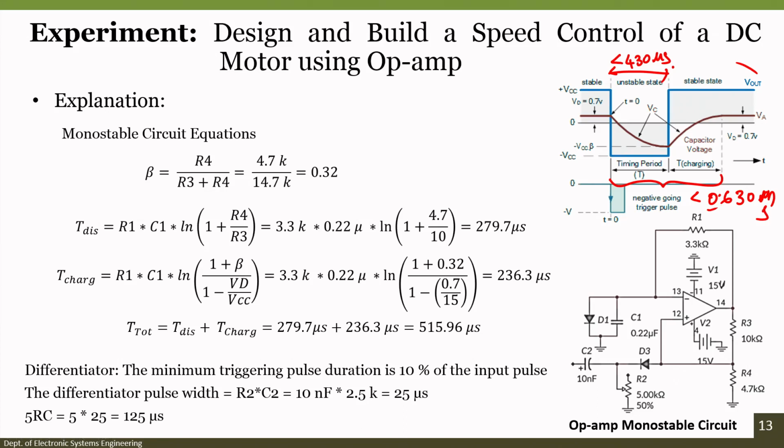If I know the formulas related to that, it is easy for me to do that. But now it is clear why we need to design for less than 430 microseconds. If the on-time of the pulse is greater than 430 microseconds, there is a chance that when the motor is rotating at a higher RPM, at one particular moment a few pulses may be missed. So, in order not to change the accuracy of the system, we will limit it to less than 430 microseconds.